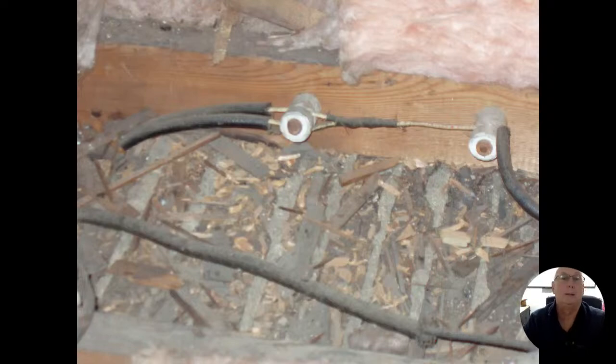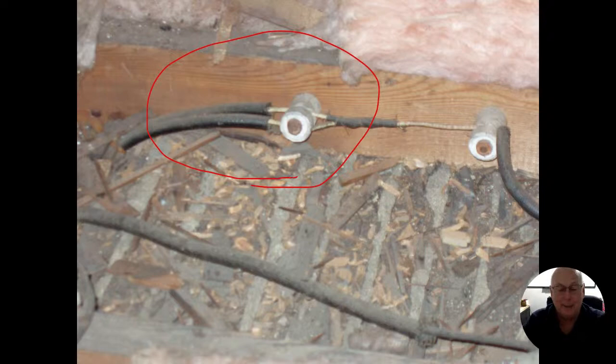This is what the old splices end up looking like. Now, when you come off the splice right away, obviously you can't get to that 3 inches right away. And what they're really talking about is between the hot and the neutral. All right. So just because it's 2 neutrals or 2 hots, they can actually be close together like this. That's not hurting anything. What we don't want to do is allow for something to fall over the top of it. Me personally, I think it should be further apart, but 3 inches is what the rule was. All right. Old splice like that, this means that was done a long, long time ago.